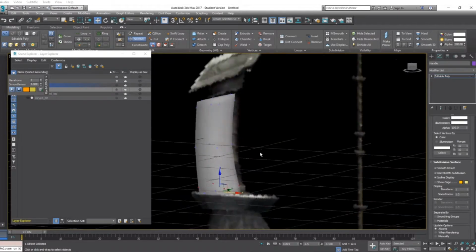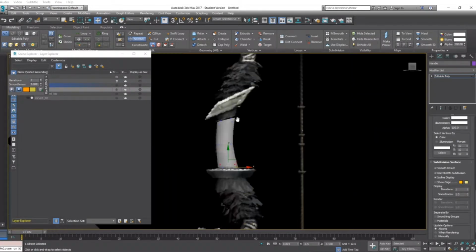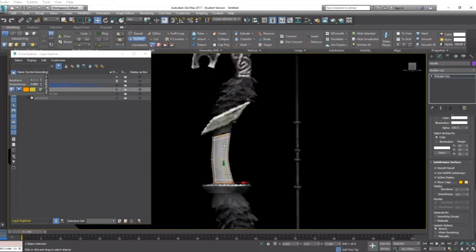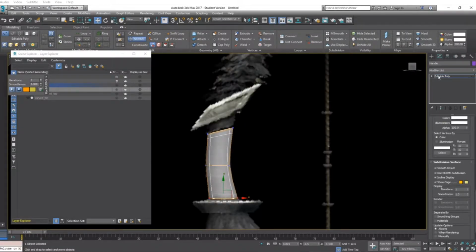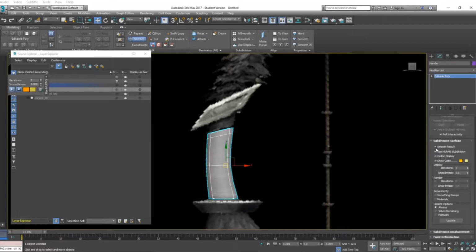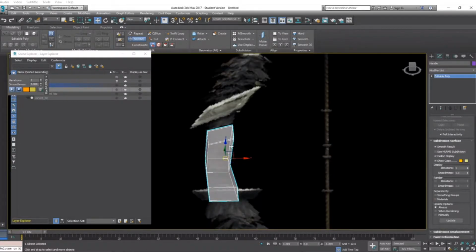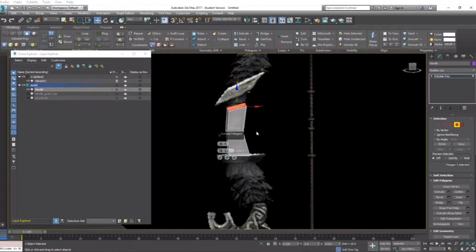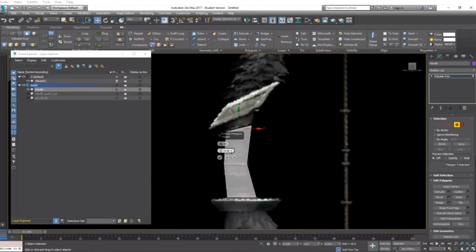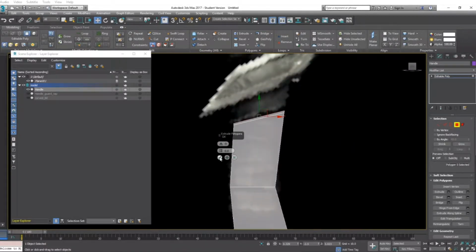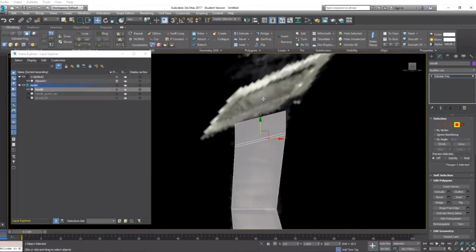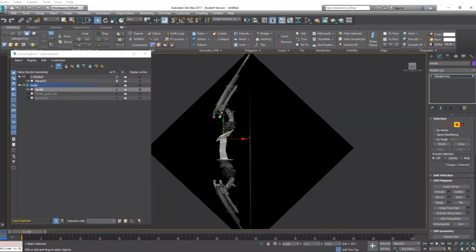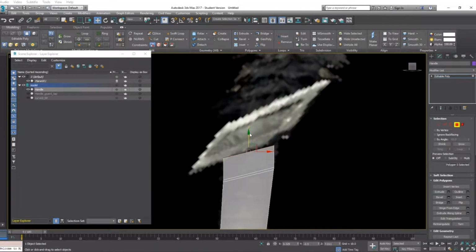So right here I notice a little black part just before the handle guard. So I decided to add that into the handle itself by extruding the top and expanding it by extruding the outsides. Now when I click extrude, initially it is shooting in an off direction. That's not the exact way I want it to be. I wanted it to just go straight up. So what you can do is put extrude at 0, and then if you drag up on the y-axis, it'll make a straight extrusion rather than having it extrude on the face's angle.